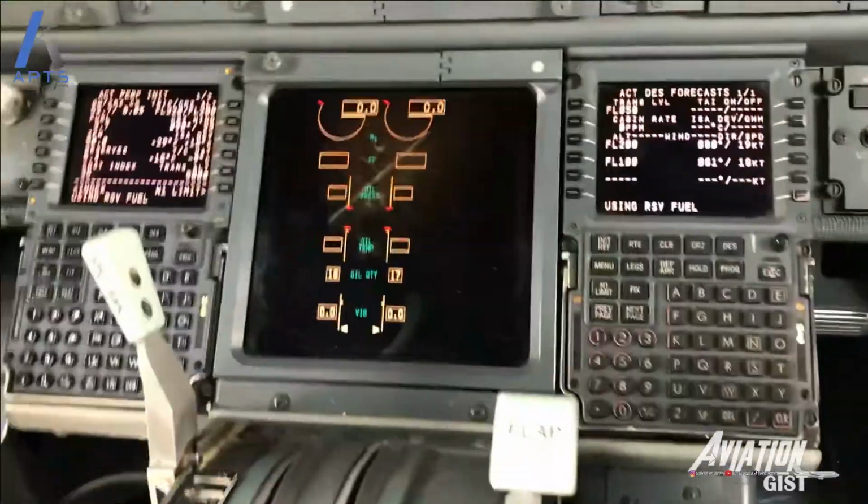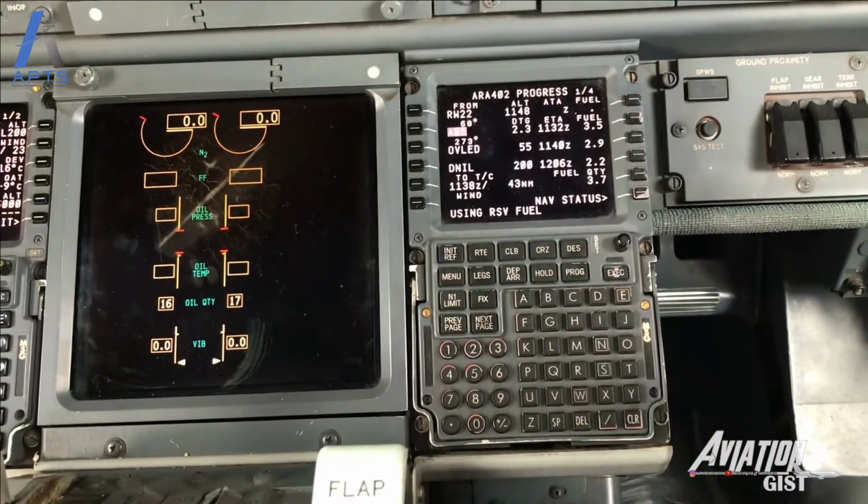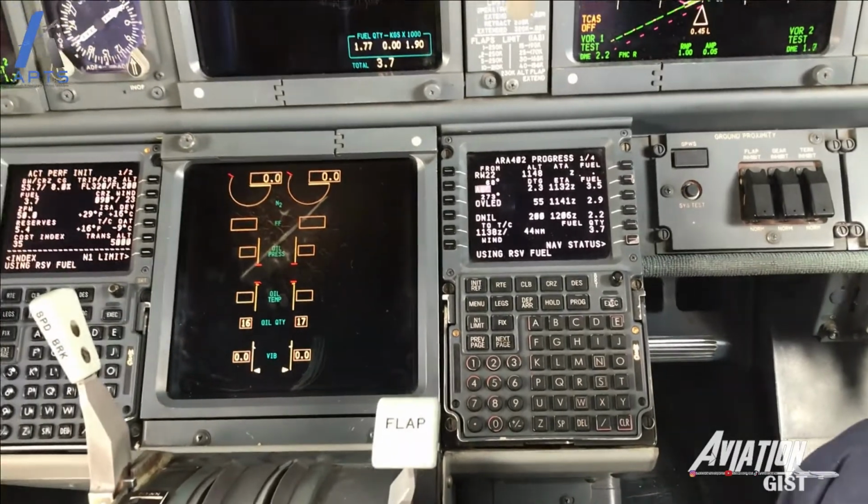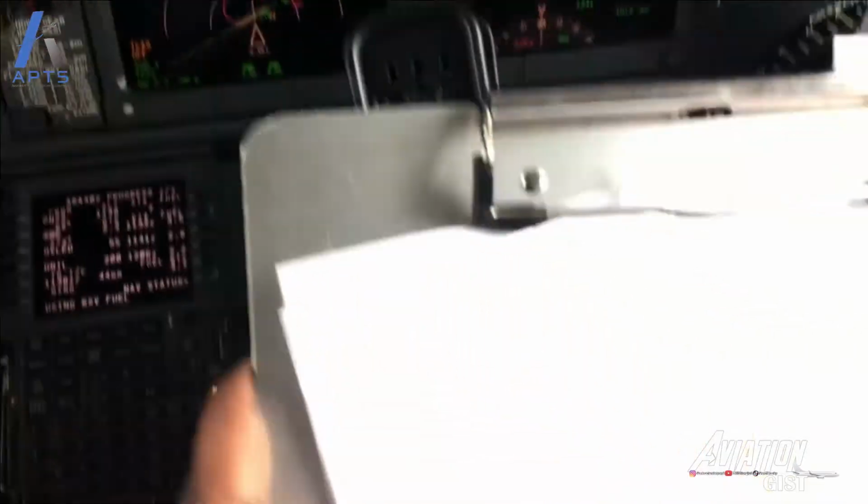Click on the Prog button to access the progress page. The first page you view is the first of 4 pages of the progress page. Here, you cross-check the summary of the routing, verify the estimated landing fuel at destination, and verify the total distance matches or is approximate to that on the OFP. This could serve as a means to catch errors in routing.